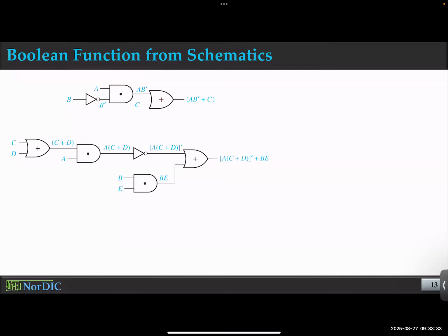And just to help you quickly remember, this is an AND gate. And if you see a circle in front of it, it represents NAND. So typically we represent inversion with this extra circle. So for example, this triangle represents a buffer. A buffer is something that doesn't change the input. Whatever input you give, you get the same output. So A gives you A. That's a buffer. You might be wondering, why would we need that circuit? It's typically used for signal restoration.